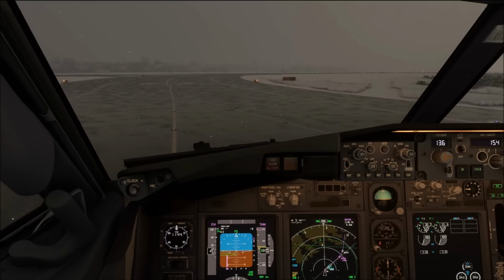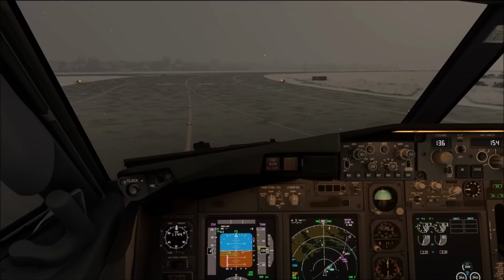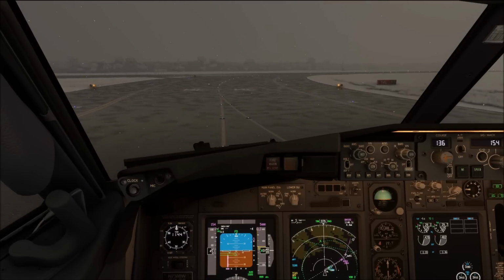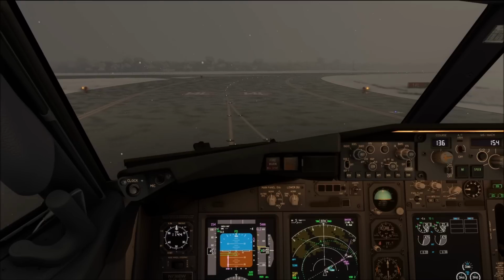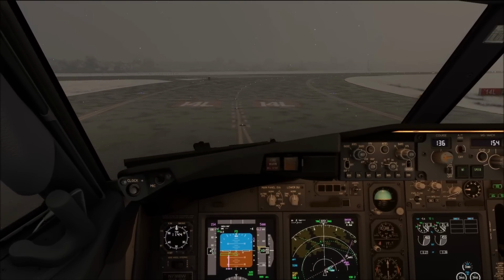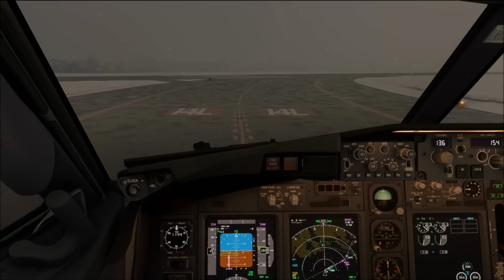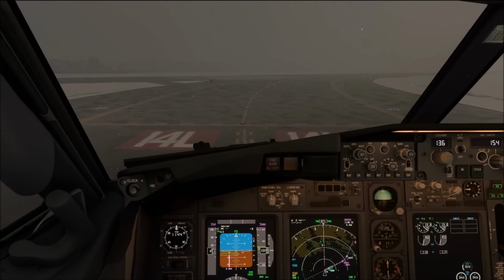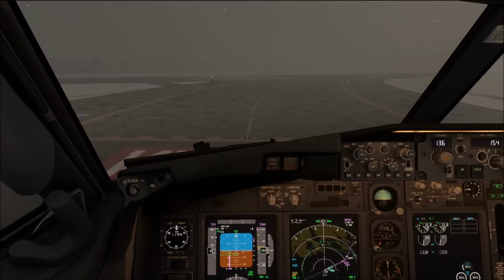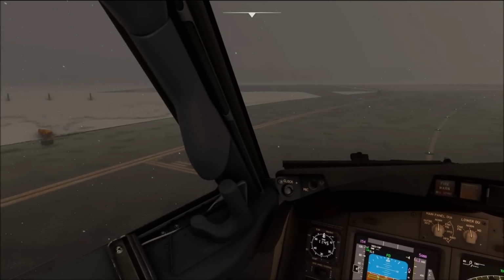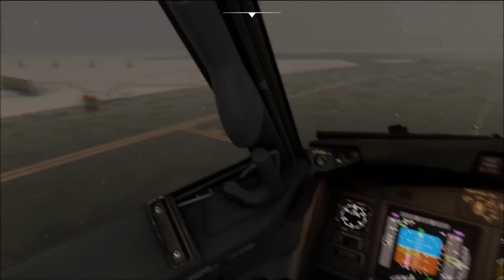Also take into account that you will need a little bit of time in order to brake your aircraft down. So we can see right now we are going at 5 knots, but I'm not going to do rapid braking maneuvers as that increases the likelihood of skidding the aircraft. So in the optimal case, I'll just go to idle thrust and let the airplane roll out. So that requires a little bit of anticipation. You need to anticipate that your aircraft will need a bit of time, but now look at how I'm slowly reducing the taxi speed.